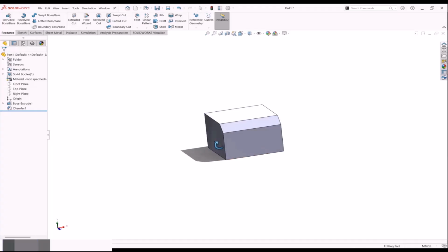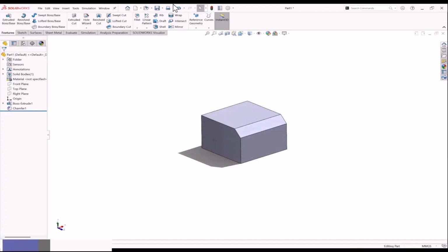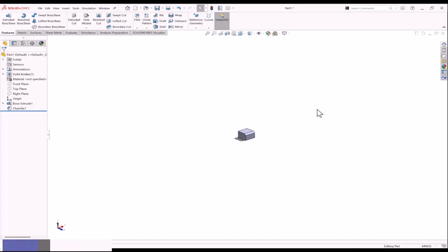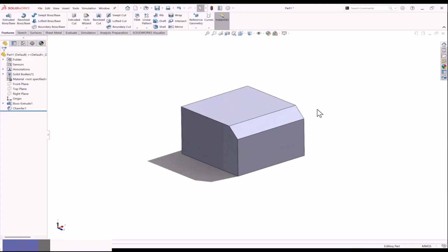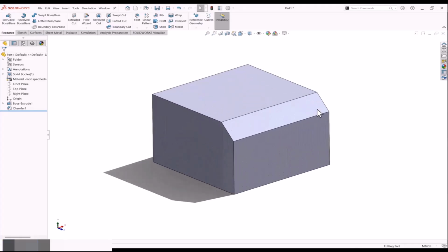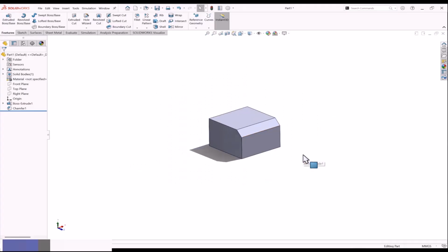Next, you want to change your view. We can use Z also, to zoom out and zoom in. That shortcut I told you, that is also there. Only Z will zoom out and Shift Z will zoom in. So these are multiple ways you can zoom out and zoom in.